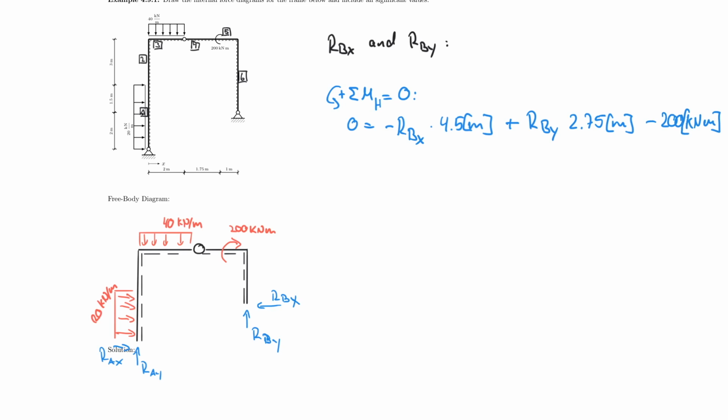And I have the first equation for my first cut, which is effectively right through the hinge and everything included. So what will I do next now? I will take the sum of the moments about the support A and include all of it in my equation. So let's set up the second equation.